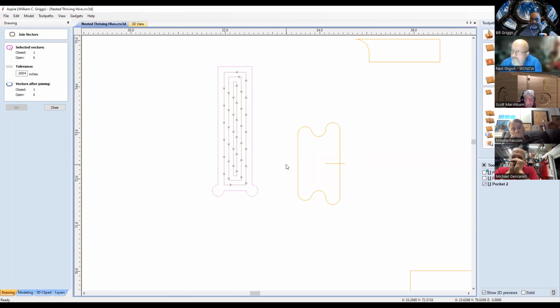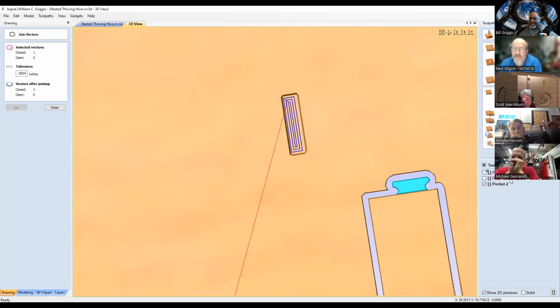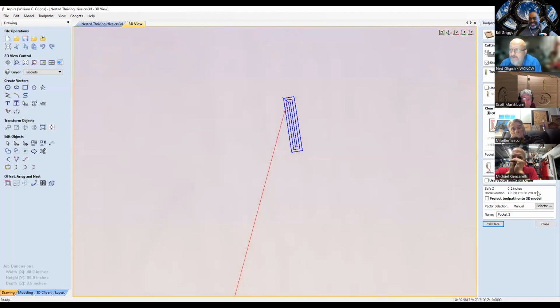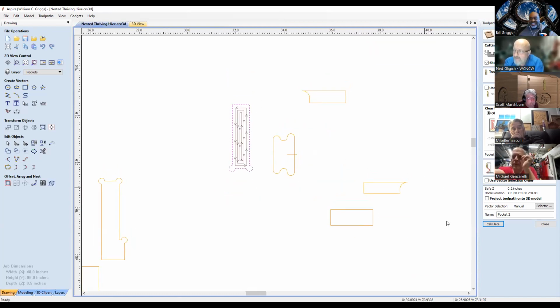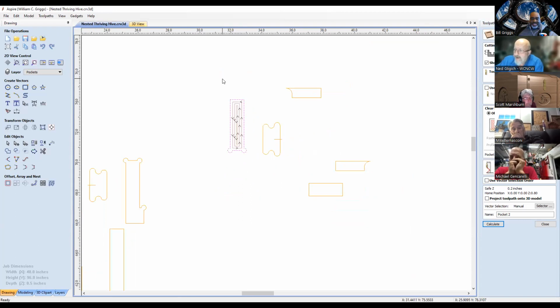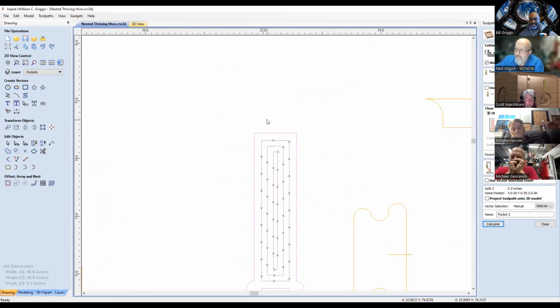Now, can you go back to the previous screen so you can calculate and do your plus minus allowance? Now zoom in on that toolpath, in 2D from above, top view. Okay, now zoom in right there, and change your allowance. Add 0.1 of an inch.